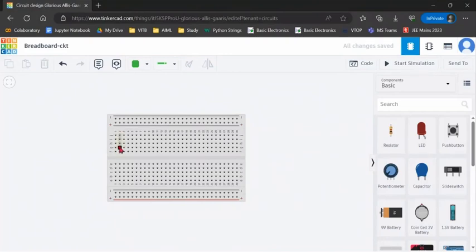In the second column, all are highlighted. That means if we connect any voltage value to any terminal in the second column, the same voltage value will be present across all the holes. Likewise, for all the vertical holes, it is the same value. That means these are shorted together, meaning these holes are connected to each other. Similarly, on the downside also, A, B, C, D, E. Column number 30 with rows A, B, C, D, E has shorted holes. These are called vertically shorted.